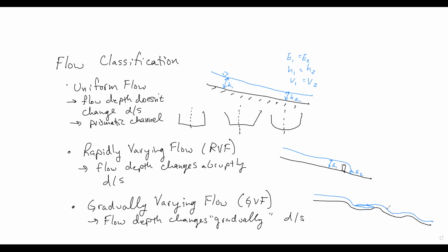And so the depth is changing in these different locations. So deep and slow in the pools, fast and shallow in the riffles. And then we also have rivers that just change their width over time. So we have kind of a meandering river from the plan view. Maybe it's wider over here and then narrower and wider. So here we're going to have shallow conditions because it's broader. Here we'll have deeper conditions potentially.